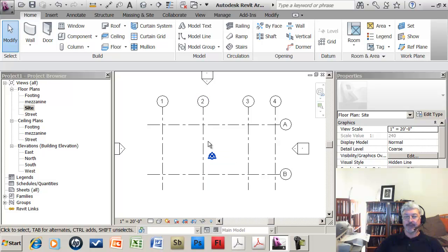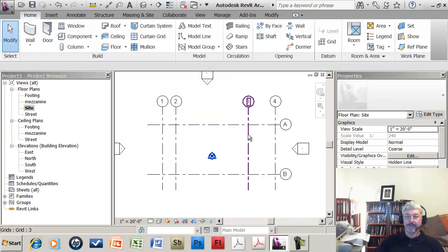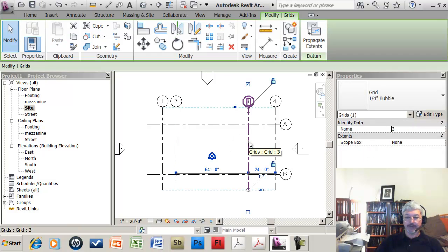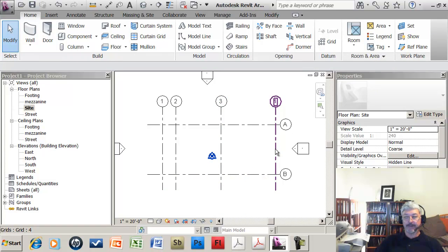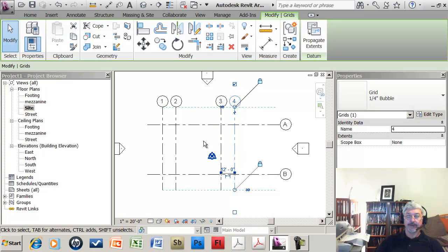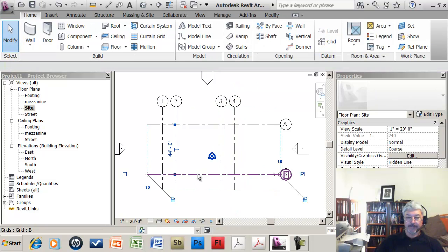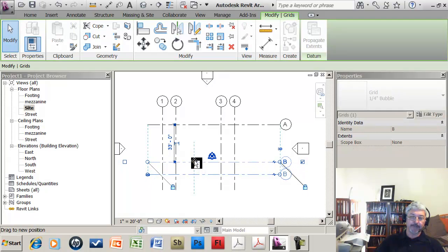The rule is that you pick the object that you want to move, you pick the dimension, and what I had said was, I think, let's say 12 feet. So if I want to have full control over this, I pick the object that I'm going to move, then I pick the dimension, and I put in the value that I want. Right? So if I pick, put in 12, or the other way I can do this is just to drag and watch the values on